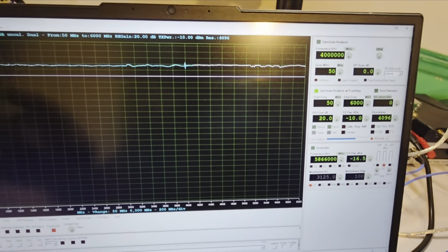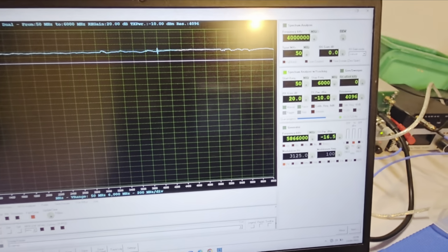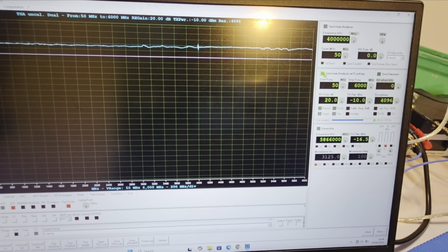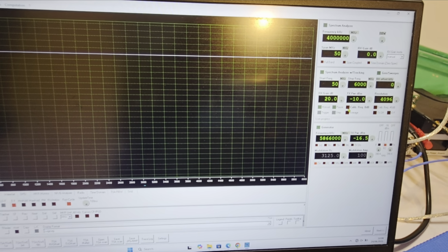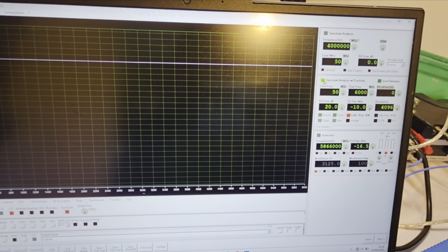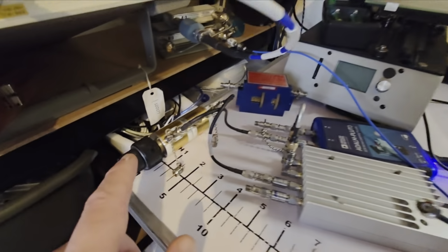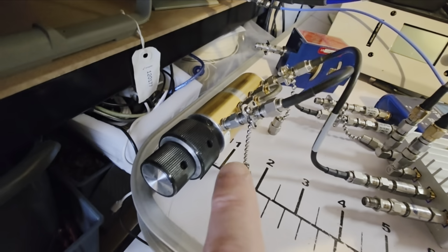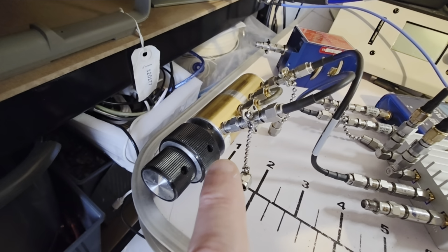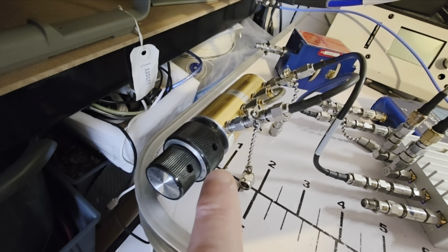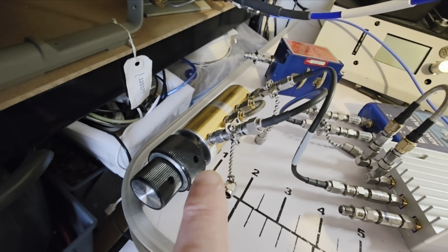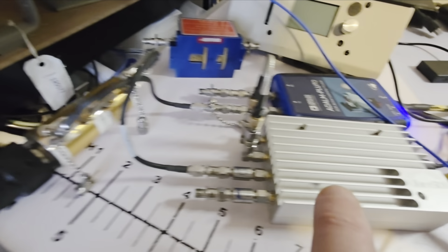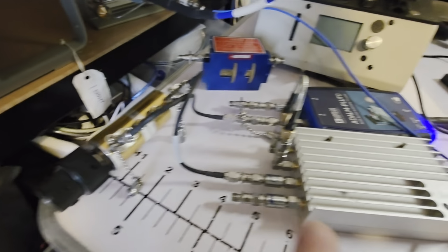So we'll make the trace, for example, I will do right now. I will normalize. The attenuator is at 0. It's a nice attenuator, an Aeroflex Weinschel or something like that. It's 70 decibels in steps of 1, and it goes DC to 6 gigahertz.